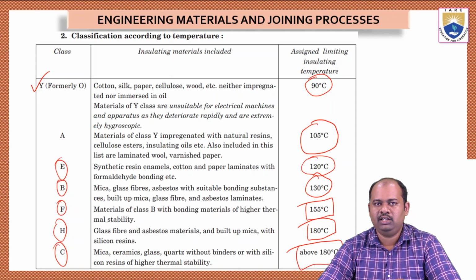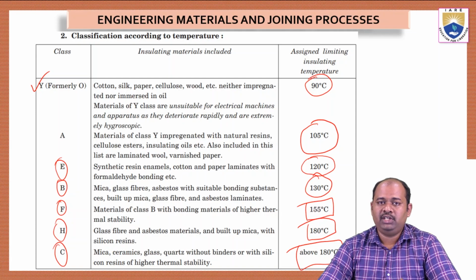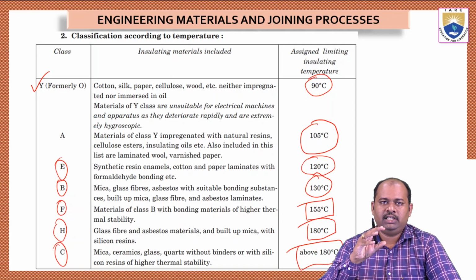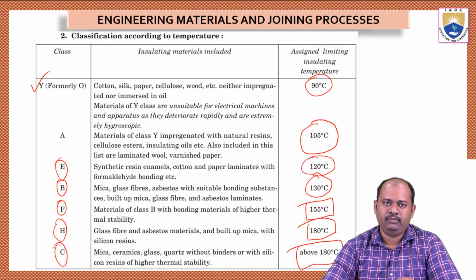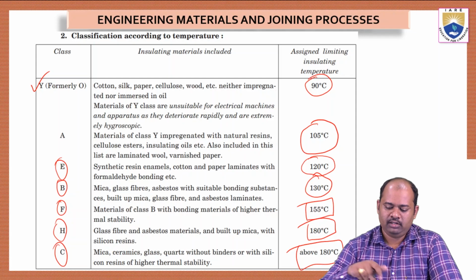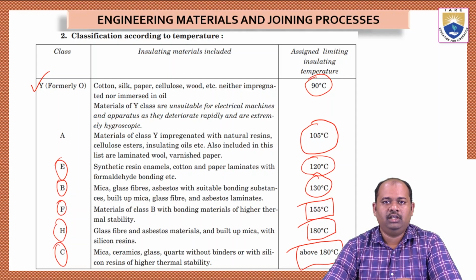Depending on the materials and their temperature conditions, the electrical resistance will change. So as engineers, we have to choose a material which correctly matches the application. And we should also keep in mind the factor of safety. We should never use a 90 degree centigrade temperature resistance material where the surrounding temperatures are around 80.